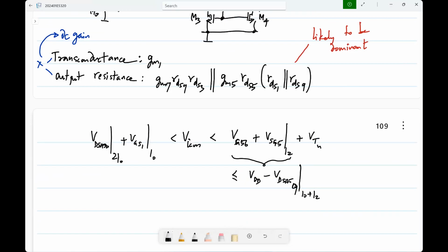So this is not very different from earlier. With an NMOS differential pair, it can go very close to VDD, or in this case even beyond. Earlier we had a diode connected transistor. Now we have something else, so this can even go beyond that. One thing you can do is put some typical values for all these op-amps and compare side by side what swing limits you get. That you can do by just inspection.